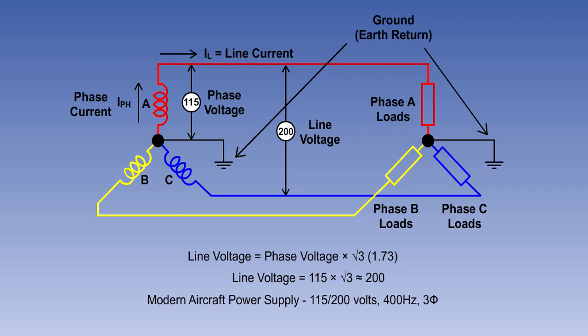While the voltages of line and phase differ in the star-connected system, because the windings form only one path for current flow between phases, the current flowing in the lines will be the same as the current flowing in the phase windings. Thus, line current equals phase current.